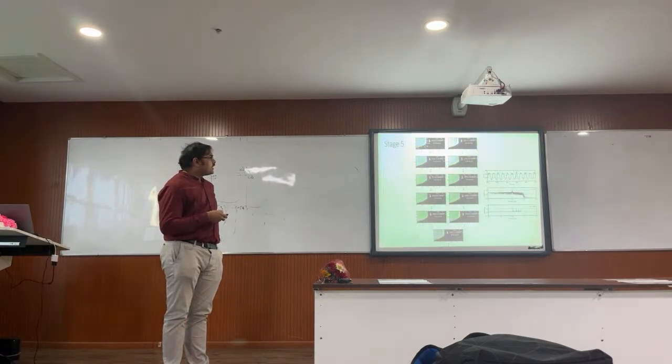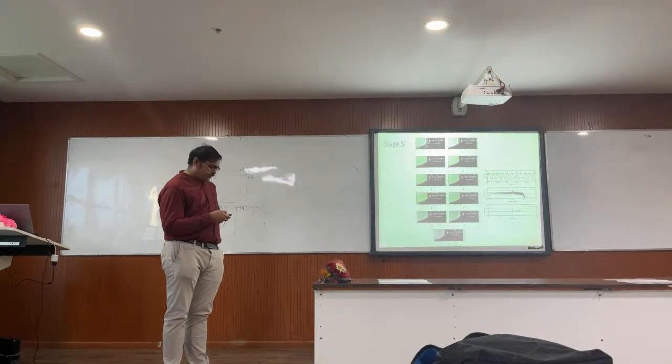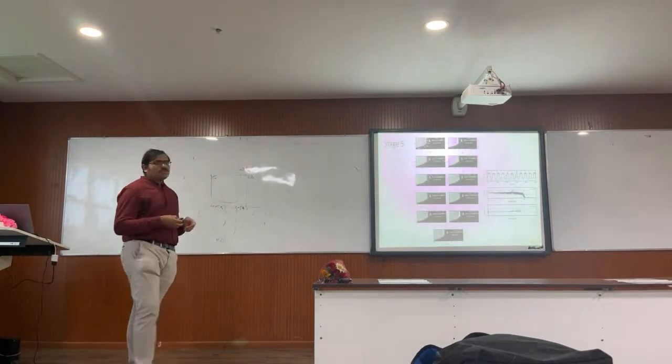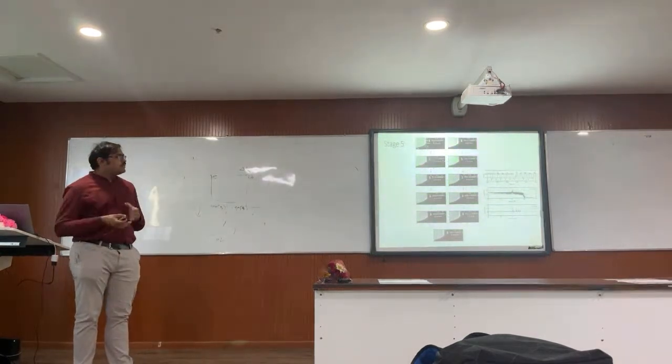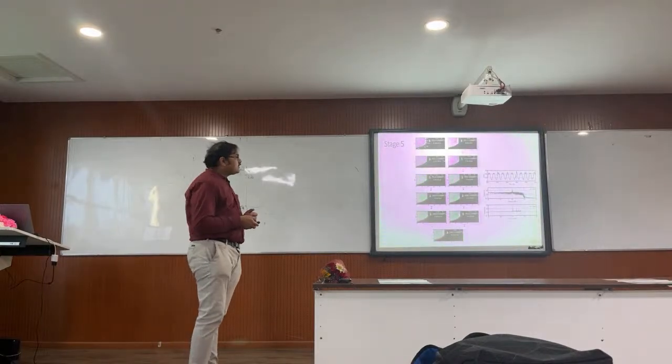Okay, and here what we see is that we get almost a near normal shock. It comes out, and then it comes out, then starts going back inside. So that is the whole cycle that it follows. So this is the case of when we changed the throttle, we see very large amplitudes and unstart.